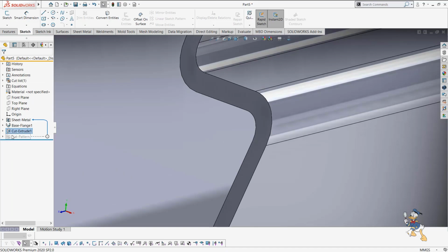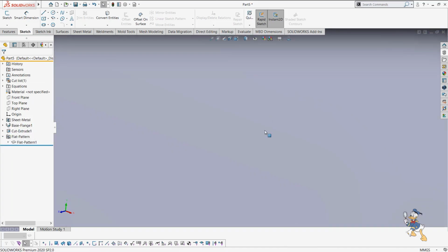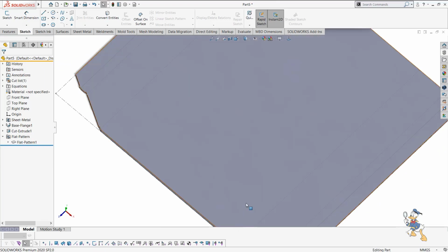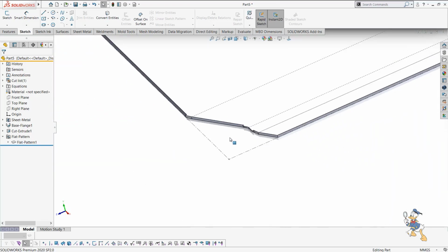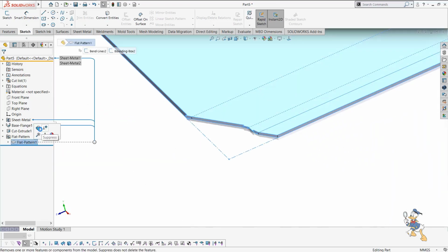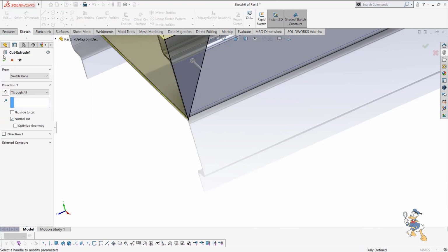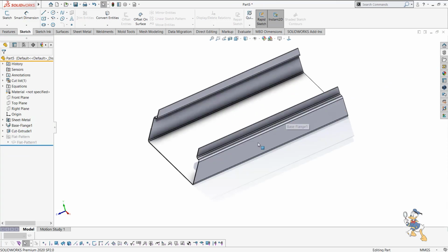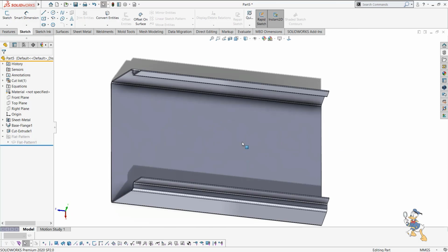But in sheet metal operation, it is not feasible with this normal cut because it will generate these kinds of errors while laser cutting the sheet metal. So we just need to use a sheet metal operation with the normal cut feature. It is a very distinguishing feature compared with other tools, not much available in competitive tools like SolidEdge or others.